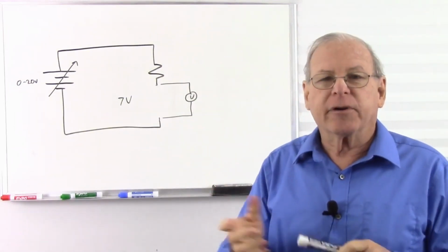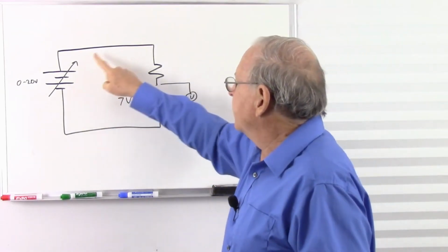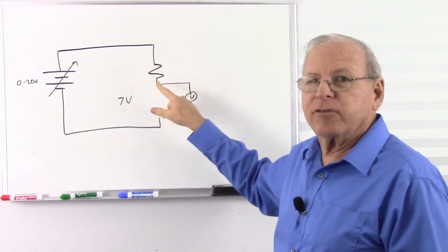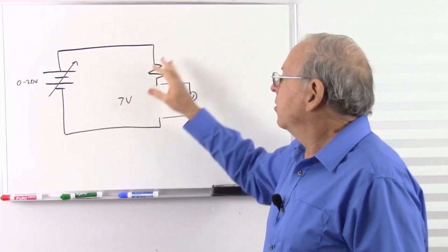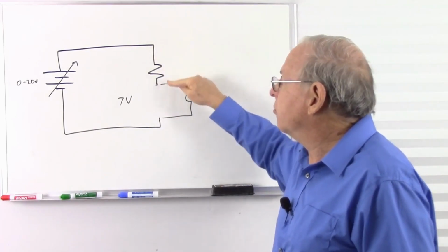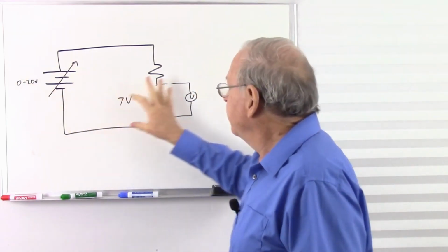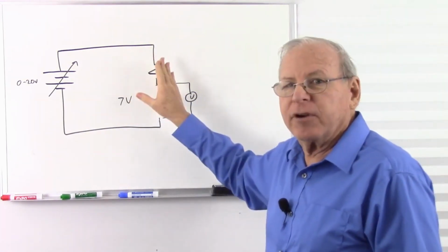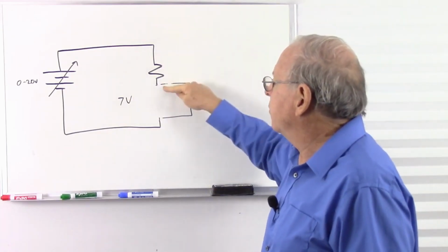And if you review the material on open circuits, which I have linked below, you will see that if we have an open circuit, there's no current. So how much voltage are we going to have across this resistor? To have voltage there, we must have resistance plus current. There is no current. So the voltage difference is 0, meaning that the voltage here is the same as the voltage here. There is 0 difference. So with this being an open circuit, I can crank this to whatever voltage I want, and I'm going to see that voltage here because there's no current. So don't forget, we may have resistance, but with no current, we have no voltage difference. And so whatever voltage we see here is the voltage we see here.